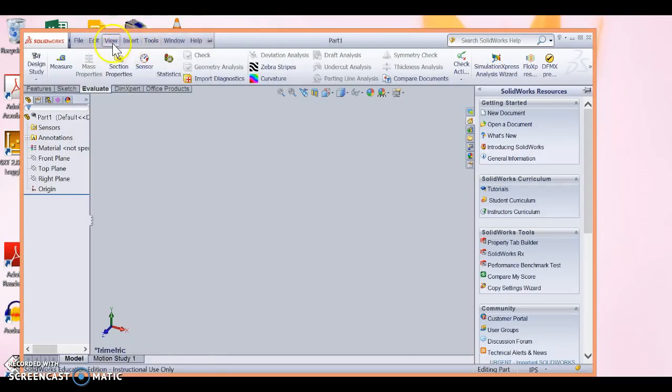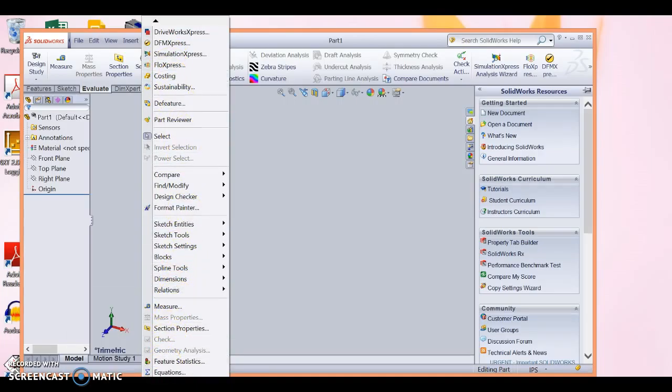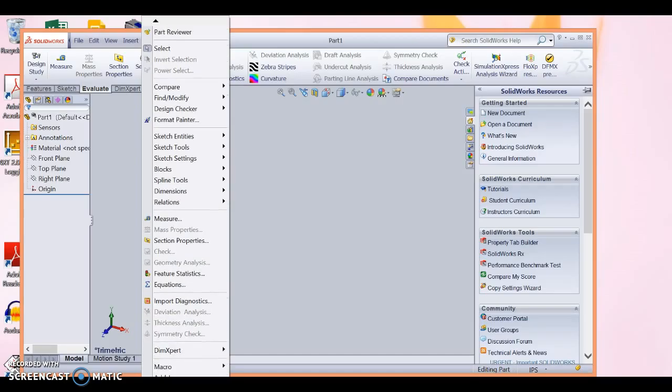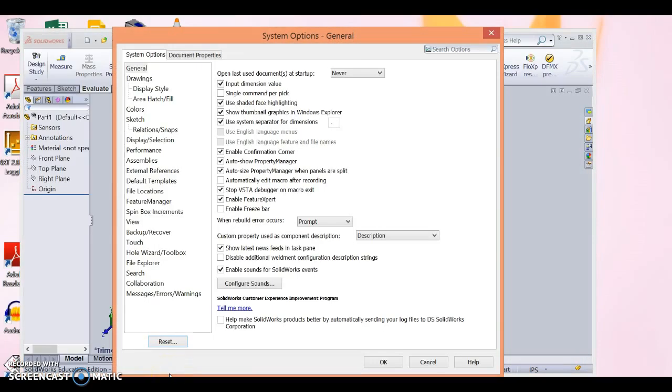toolbox, and then you have to go over to, this is really a pain in the neck, the Tools drop down menu, and then you're going to scroll all the way down, and it's actually off of the screen here for you, but there is an option here. I think you might be able to see it says Options. Click on Options under Tools. And then once you click on Options under Tools, you're going to find over here on the left side it says Units. Where is